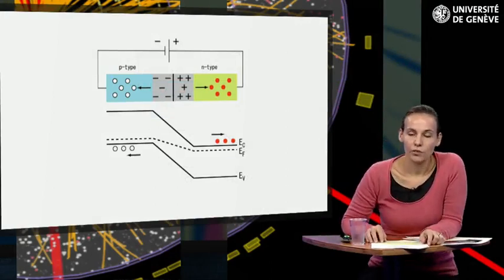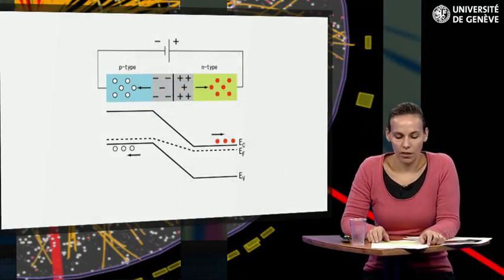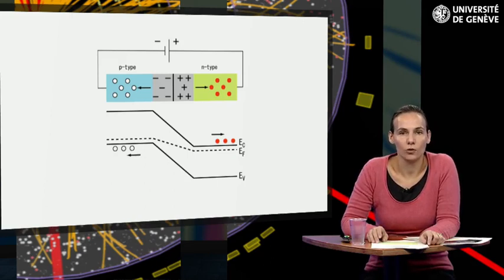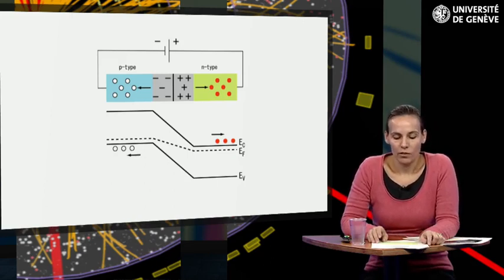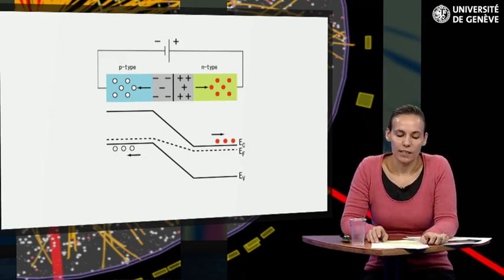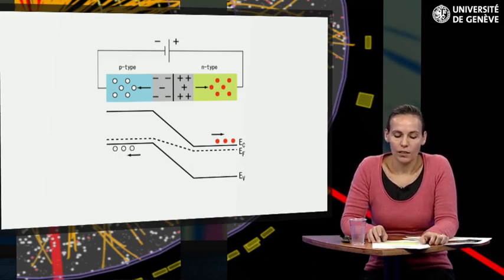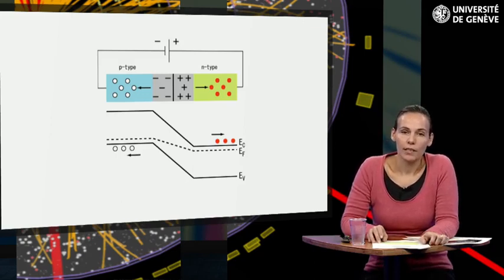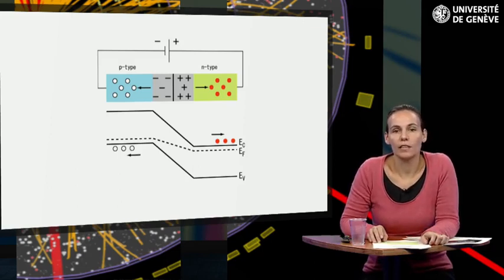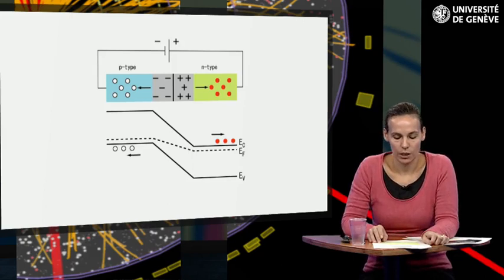Semiconductor detectors have a good efficiency since only 3 electron volts are necessary to create a single electron-hole pair. So these detectors are 10 times more sensitive than a gas and 100 times more sensitive than a scintillator. It therefore has a lower detection threshold and a better energy resolution, since more primary ionization means less signal fluctuations.